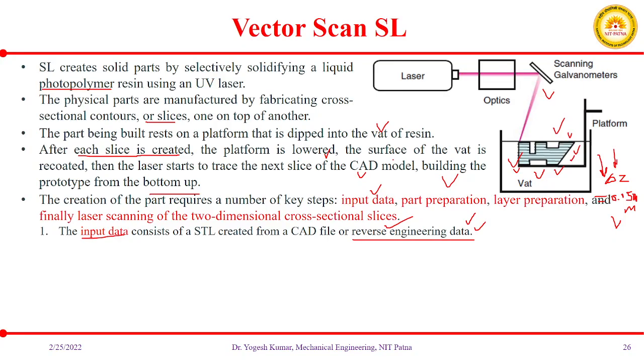So yes, input data. Okay, so we were talking about the input data. We are either creating a CAD model as your input data, or from the CAD model you are creating your STL file, or you are collecting data by using the reverse engineering method. Maybe you may use a 3D scanner in order to get your data corresponding to your CAD model. Okay, so this way we are preparing the input data.